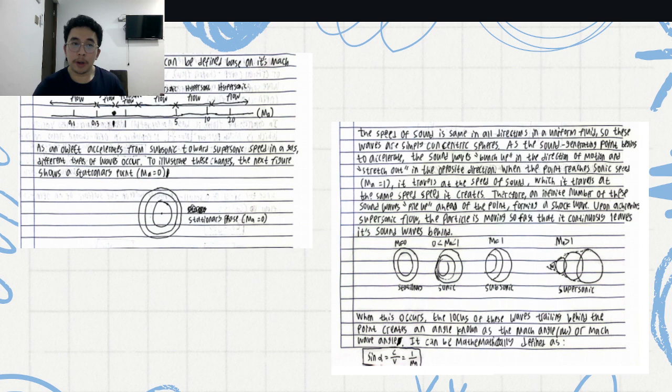If an object travels at the speed of sound or above, it creates a shock wave, which we can illustrate like this, and the compressibility effects start to occur, forming a wave that's sort of like a cone, which at the point creates an angle called the Mach angle. This is supersonic.